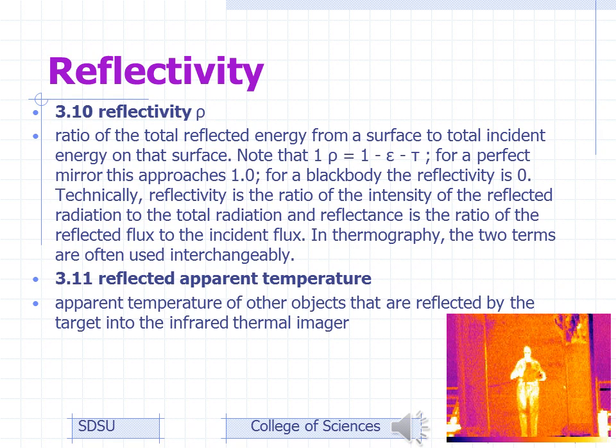I'm a little bit cooler at the skin surface, of course, than the device itself, which is at 98, 99 degrees Celsius. So I look higher. I look hotter, 98 degrees. I'm sorry, I use Fahrenheit on myself, but I look hotter than the device, and I'm simply not. I'm a lot cooler than the device itself, but I look hotter in here because it's additive. What you're looking at in my body image area is that heat, which is incident on it from the surface and reflected, in addition to that which is radiated out, and that's why it looks hotter.